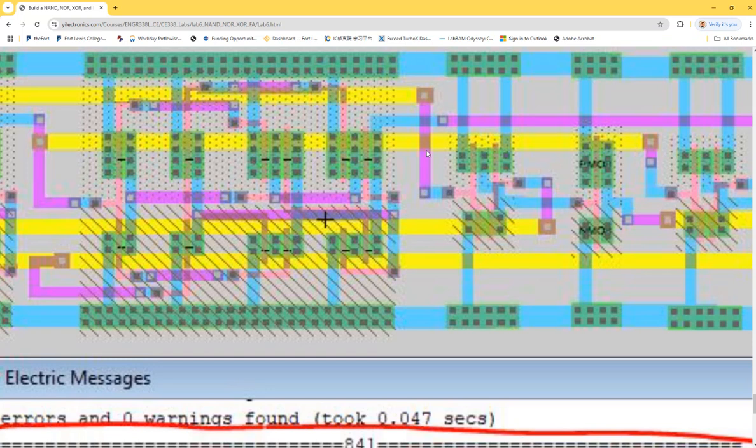Okay, and then I have to connect to the yellow color, which is metal 3, because I know there are metal 3, metal 1 in here. So I have to cross these two metals in order to make the connection to here. So in that case, I have to drill a hole to metal 2. That's why last time someone was asking, why do we need 3 metal layers? That is why, right?